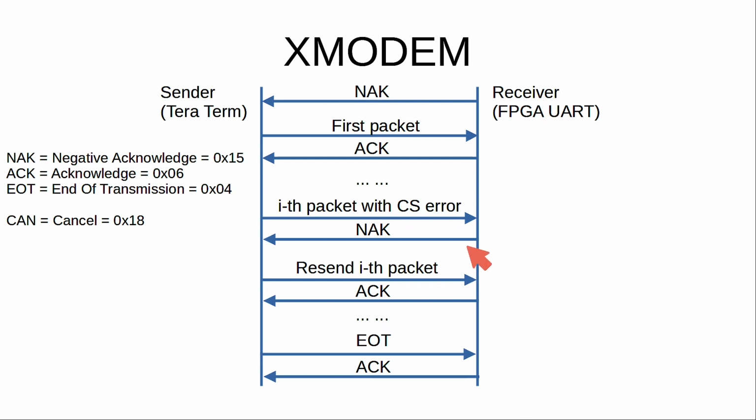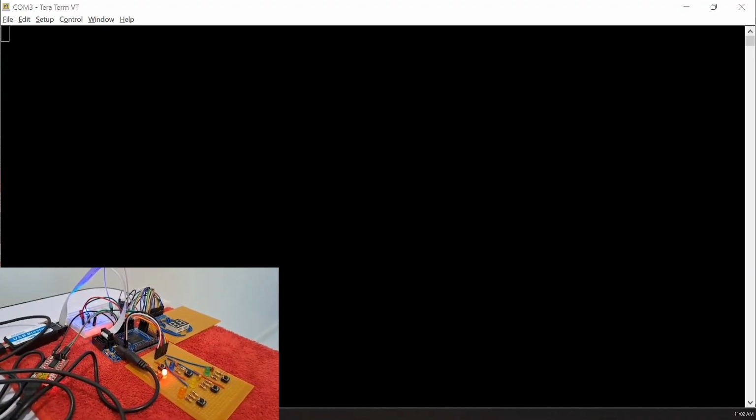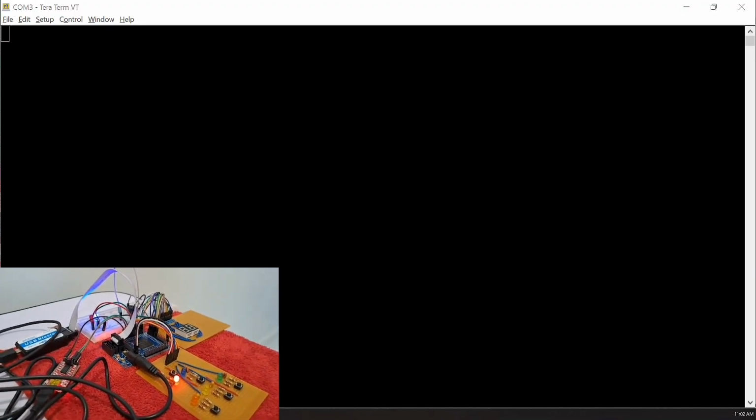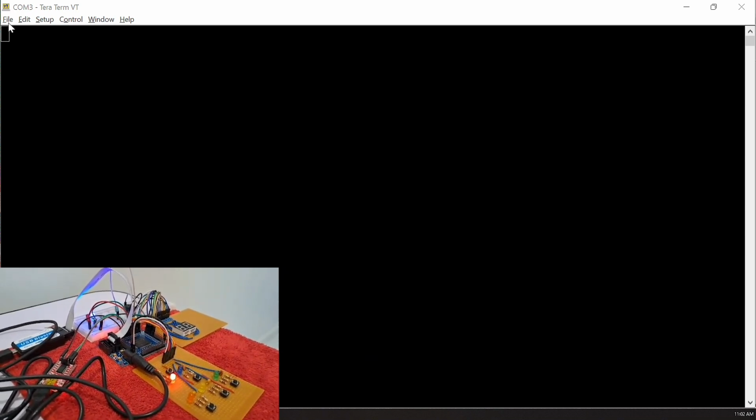In our loader program, for each of the packets, we will extract the data bytes from the packet and then write them into the RAM region. And when the transmission has ended, our loader program will jump to the RAM region and start executing there. Let's see the transferring of the binary data from our laptop into the FPGA in action.